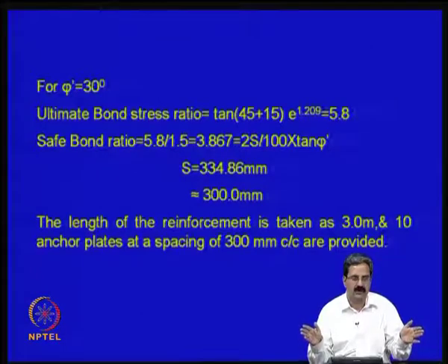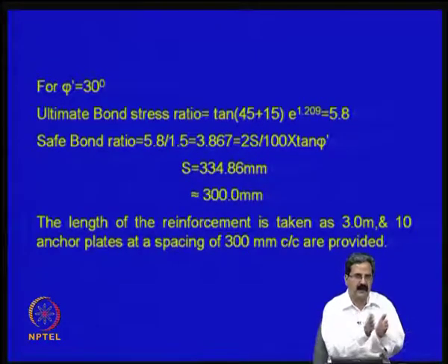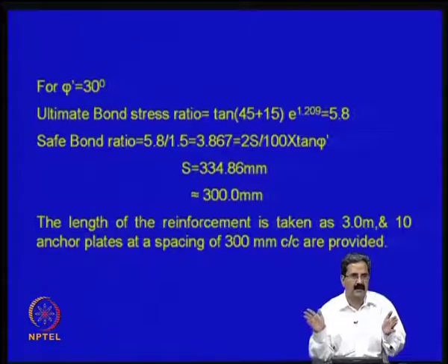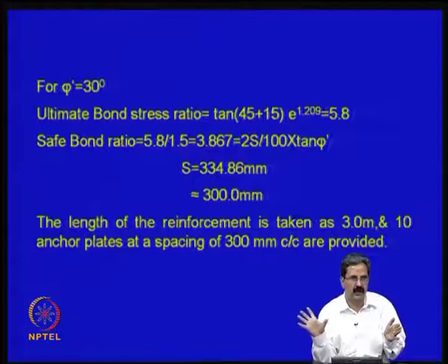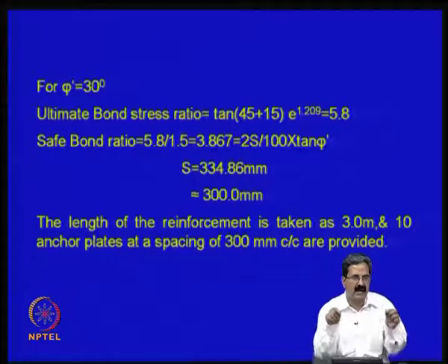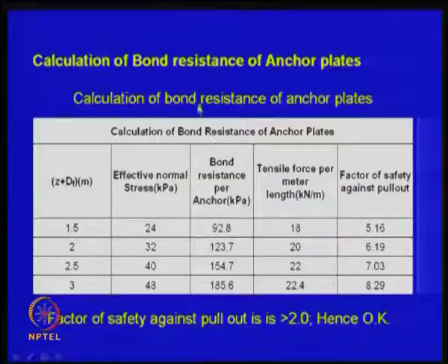You should also have seen the x naught numbers. X naught is a part of the total length L naught; L naught minus x naught will give you the pull out resistance, and x naught is the length at which the location of maximum shear stress occurs. So, with this spacing one can go ahead, and if you want to calculate how it looks, you can see that. Is it okay?